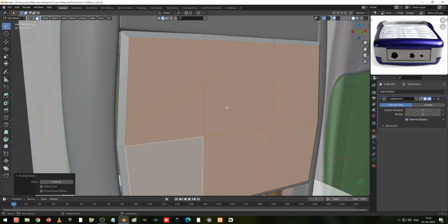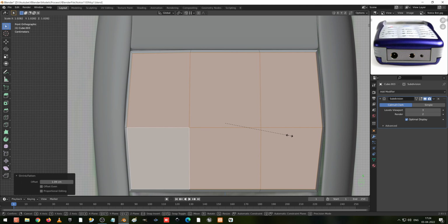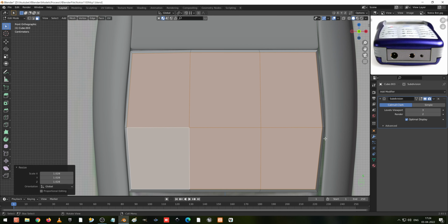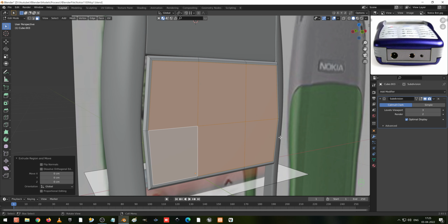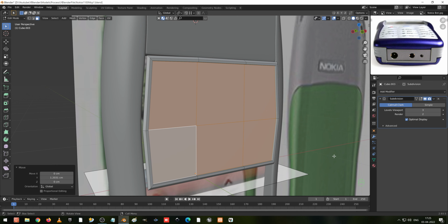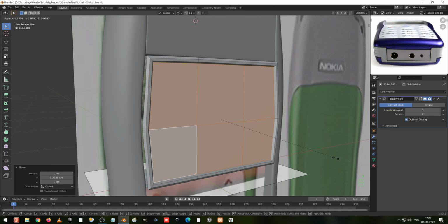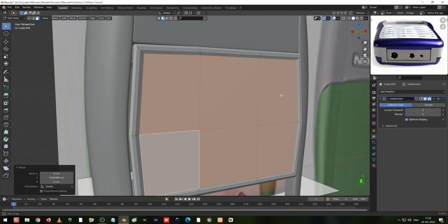after doing this, I'll go to front view and I'm going to scale it slightly out, and I to insert, and E to extrude in the y-axis, G and y-axis, slightly inside and scale it, and GY to move slightly outside.